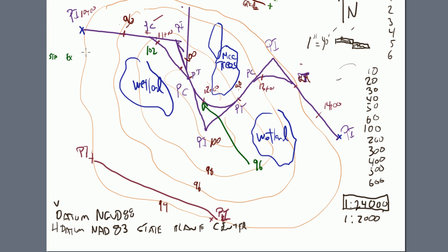Alright, you have something that looks like station, existing elevation, proposed elevation, and then cut and fill. So here 10 plus 00, 11 plus 00, 12 plus 00, 13 plus 00, 14 plus 00, 15 plus 00. You get your existing elevation, you get your proposed elevation, and then you have your cuts or fills. Alright, so there's one sketch.